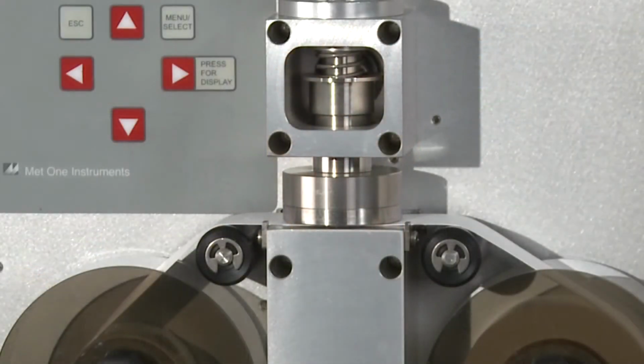Almost all air leaks in the EBAM system occur where the nozzle contacts the filter tape. The EBAM has no way of automatically detecting a leak at this interface. This is because the airflow sensor is located downstream of the filter tape. There will normally be a small amount of leakage at the tape, but an excessive leak allows an unknown amount of air to enter the system through the leak instead of the inlet. Allowing a leak to persist may cause data to be invalidated back to the last known good leak check.